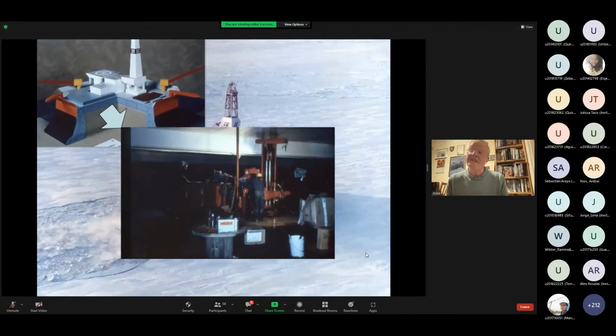So we did a lot of CPT testing to understand what our sand was like. In the picture you're seeing here, notice we've got a deck. That's actually a box girder deck with storage and offices in it. But underneath it, there's an air gap. And this is the air gap. So that's the underside of the box girder deck, and that is a sand surface that you can't quite see. And this is where we're doing some CPT testing. We did a lot of it.